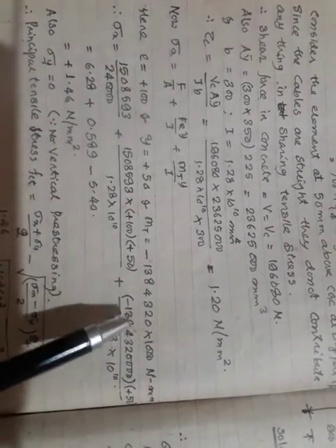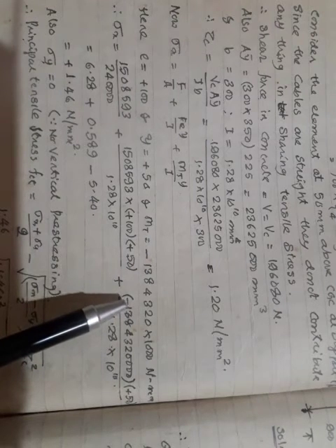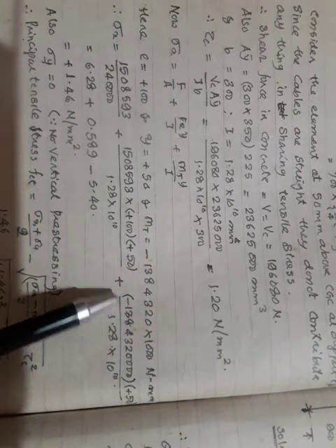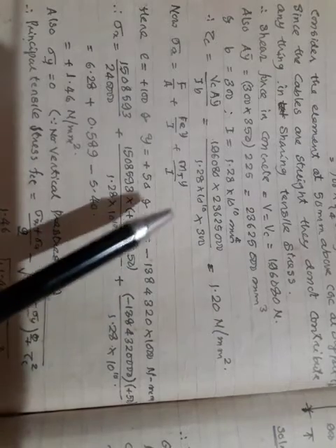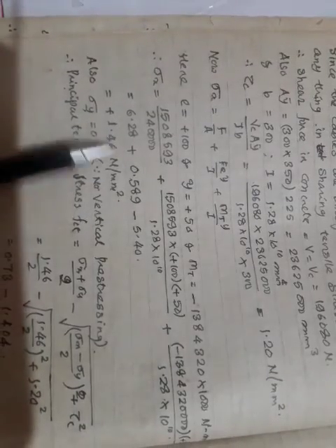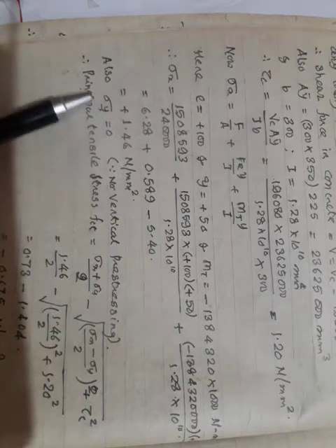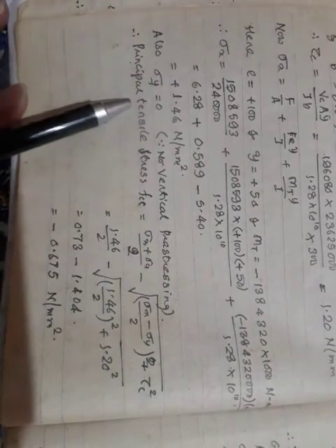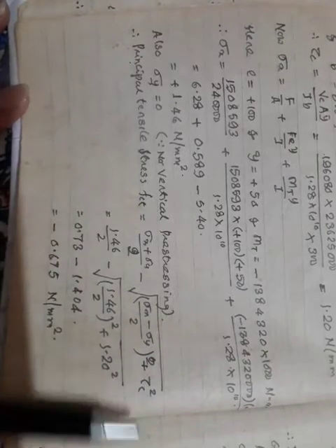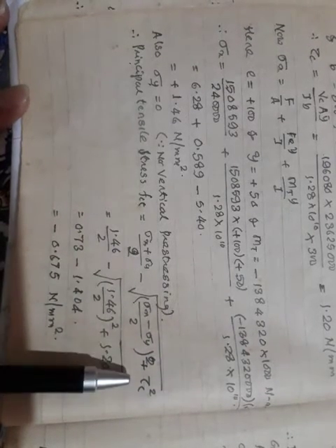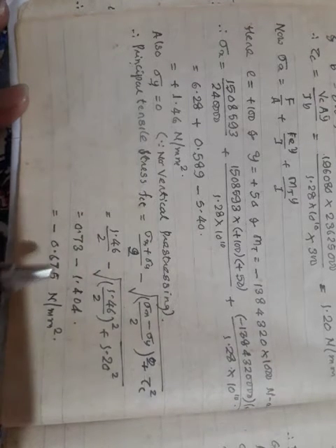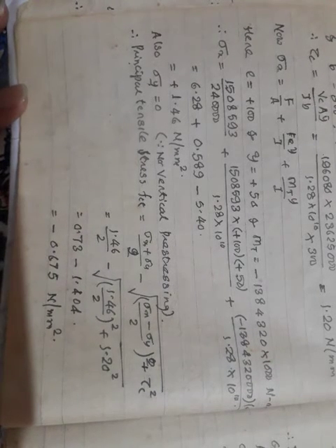Okay. Mt, the bending moment you have already calculated, but your bending moment you have to give a negative sign because it's a cantilever. Okay. So y I know. Okay. Again I. So it will become sigma x is equal to 1.46. Since vertical pre-stressing is absent, sigma y is absent. Sigma y is 0. So now I want to calculate the principal tensile stress by this equation. Okay, you know this equation very well. So fill up all the values, sigma x you know, sigma y you know, tau c you know. Okay, and find out the value of this principal tensile stress. That is what he has asked. Okay, thank you very much.